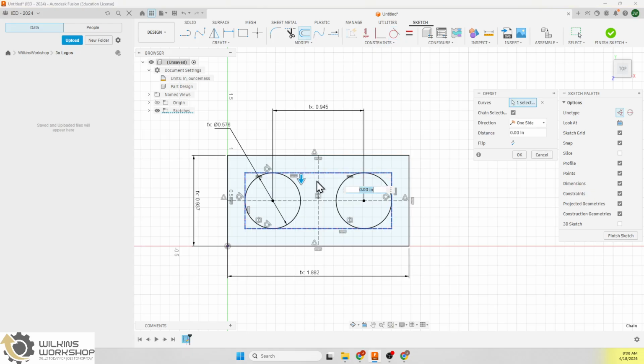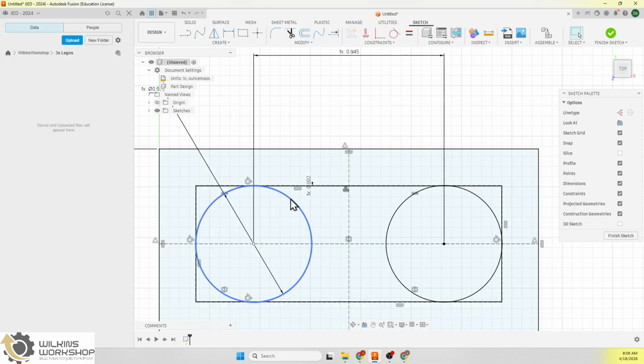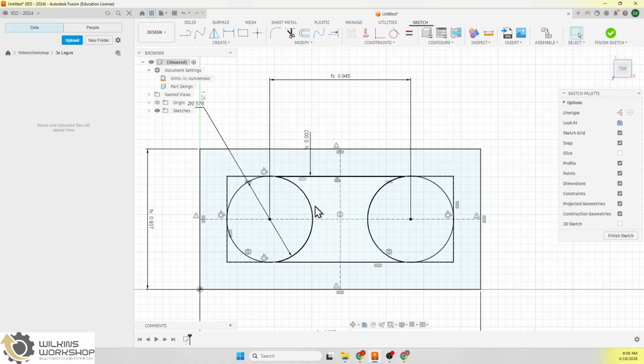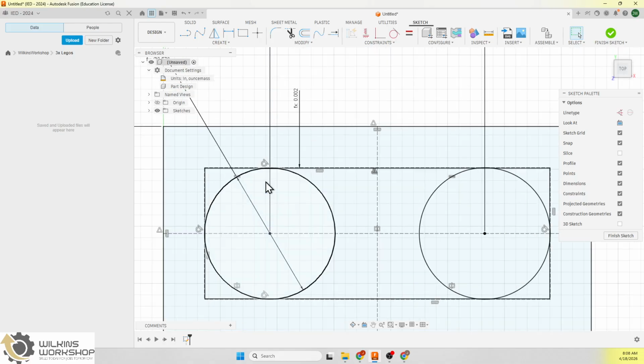So when I do an offset, I'm going to do kerf divided by 2, is what we have found for most pieces. Now I'm going to put that in there for most pieces because if you have at least 2 studs that you're gripping onto, this seems to work great. If you only have a 1 by 1, then we usually just do this as kerf. So it squeezes a little bit tighter.